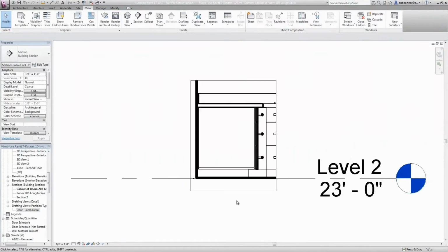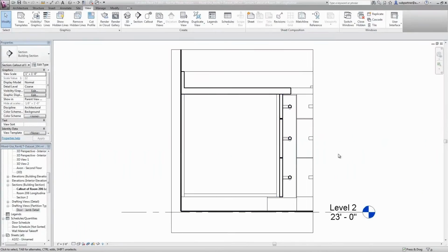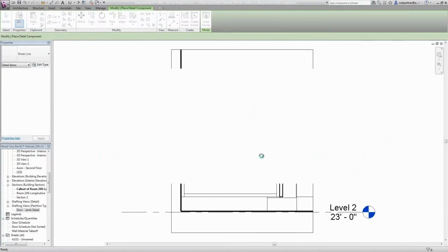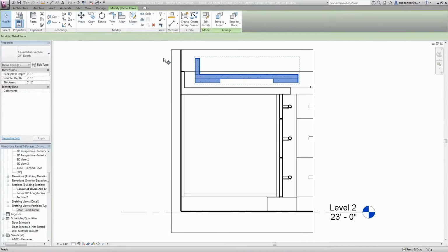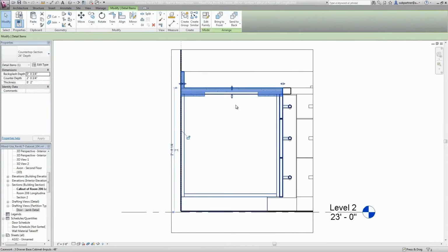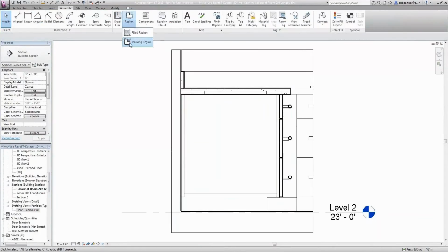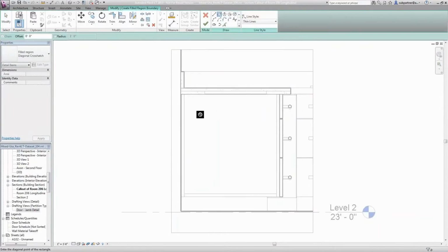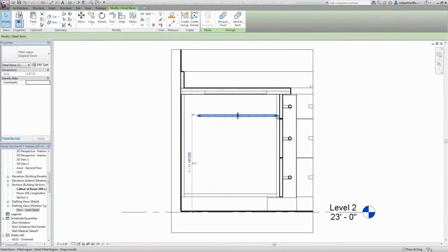Or I can use a 3D model. So I did some callouts here. I made the view on the 3D model, but I want to have it in bigger detail. And now, in fact, I will overlay the 3D model with my detailed parametrical tools, which you saw in the very first point. So I am putting these parametrical 2D tools on top of the 3D model, setting up the constraints, and what can even happen is that these tools will be reacting if I'm changing something in my 3D model. These tools will be reacting and changing.